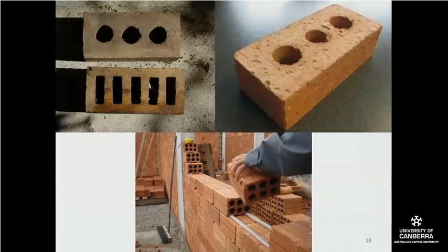The other type of brick is what you call an extruded brick. So essentially it's pushed through a brick-shaped mold, and then they use a wire cutter to cut it exactly to the height that is required. The top two versions are kinds of extruded bricks that we might find in Australia. This one I was thinking was quite uncommon until I looked at the brick that I'm using as a doorstop, and it's exactly this. But there are many other forms of extruded bricks like these ones here, which they use in Europe and also in certain parts of Southeast Asia. I think this is a French tradition, because this is how they make bricks in Cambodia.